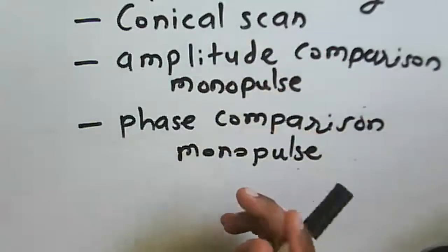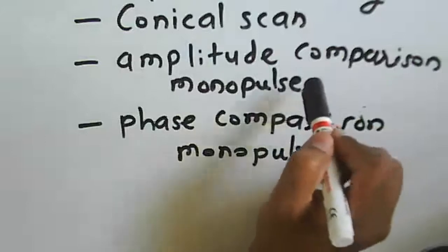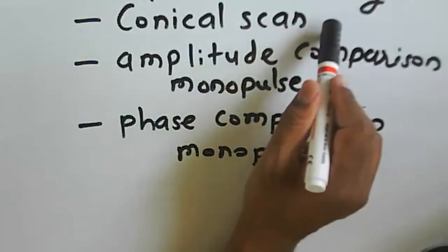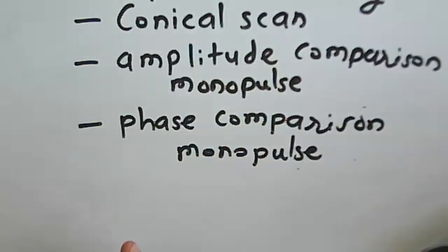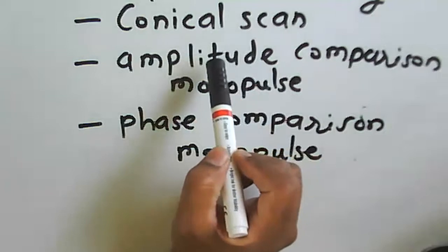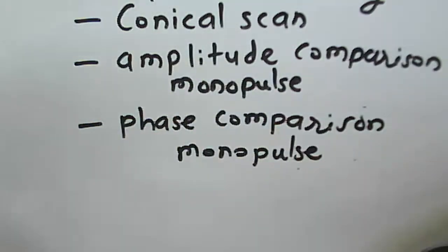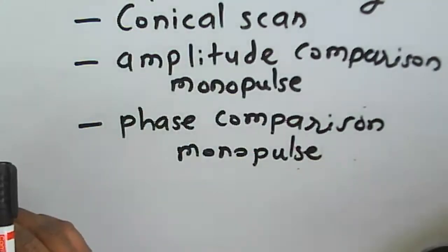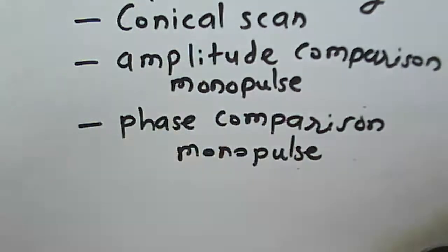If you compare the signal to noise ratio, monopulse tracking is better than the conical scan radar. Accuracy in terms of angle is also better in a monopulse radar, but not in a conical scan radar. If there is a small variation in the angle, the angle accuracy will not be affected by the fluctuations in the echo signals we are receiving in a monopulse radar. Similarly, even if there is a small variation in the angle accuracy, it will not affect a conical scanning system.